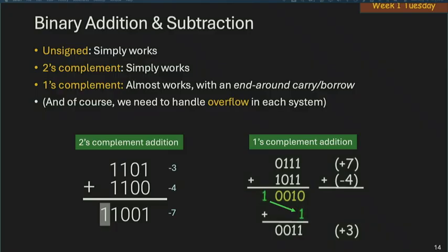How do you get 15 or 16? Do you just remember? You could. I'll show you 3 ways. Number 1 is to remember this negative 15, negative 16. Number 2 is to remember that for 1's complement, you complement by flipping the bits. So take a positive number and a negative number, say 0011 and 1100. These are 3 and negative 3, respectively, and they add up to 1111. This is an alternative definition of 1's complement: negative and positive numbers relate by 15 in unsigned.